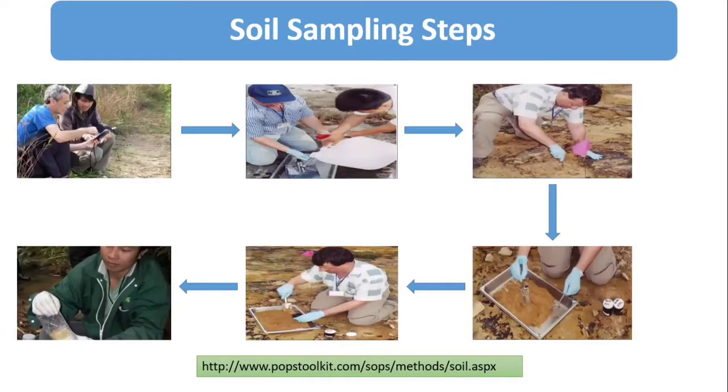So once you reach each location, you have to note the latitude and longitude. Then thoroughly clean all sampling equipment like dredge, mixing tray, spoon, etc. with metal-free soap and deionized water prior to sampling at each site.